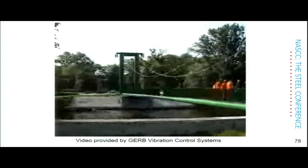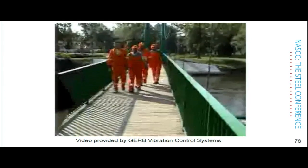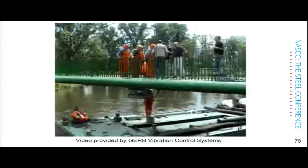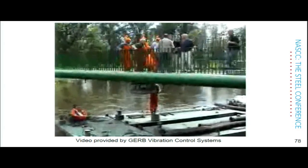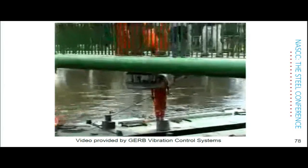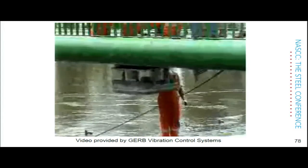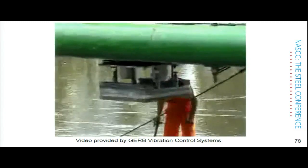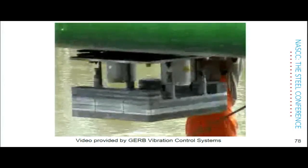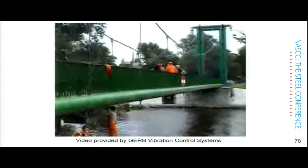There's a number of pedestrian bridges in Las Vegas. They're having trouble walking up. In Las Vegas, along the strip, to prevent that kind of thing happening at 2 o'clock in the morning, they have TMDs in them. Very effective for pedestrian bridges because they're one mode, basically. And it's a very, very simple response. You start putting them in an office building, it gets to be more tricky.